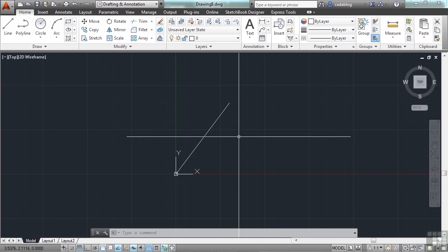And this is how surveyors will draw in AutoCAD. They will typically need to work on some sort of coordinate system. In the United States, we use a lot of state plane coordinate systems, and their origin is set at some arbitrary point in the real world. That's at 0, 0. And then they may go thousands of units away because they're usually covering large areas. And you can draw from point to point. So this is a very useful and just another way of drawing in AutoCAD.